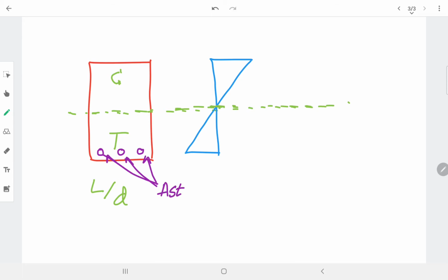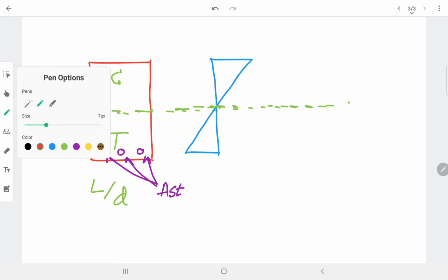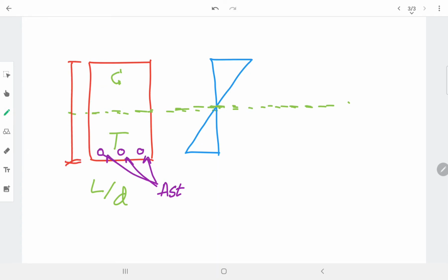Whereas what happens, you are not happy with the overall depth of this beam, so I will be restricting the depth to some extent. Suppose D is equal to 900 mm, so this is quite high, so I will be restricting the depth, making this beam 600 mm.